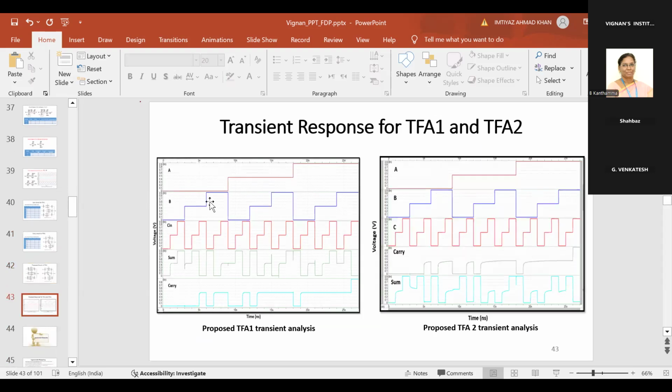This is the transient response. I've explained the transient response previously using A0, A1, B0, B1 and C0, C1. But in ternary circuits, as I explained previously, there are A0, A1, A2, B0, B1, B2, for three conditions, three logic levels, 0, 1, 2, 0, 1, 2, 0, 1, 2. Why are we using different timing responses? Because this time for A0, all combinations of B, and for B0, all combinations of C, we get all combinations of A0, B0, C0. Okay?